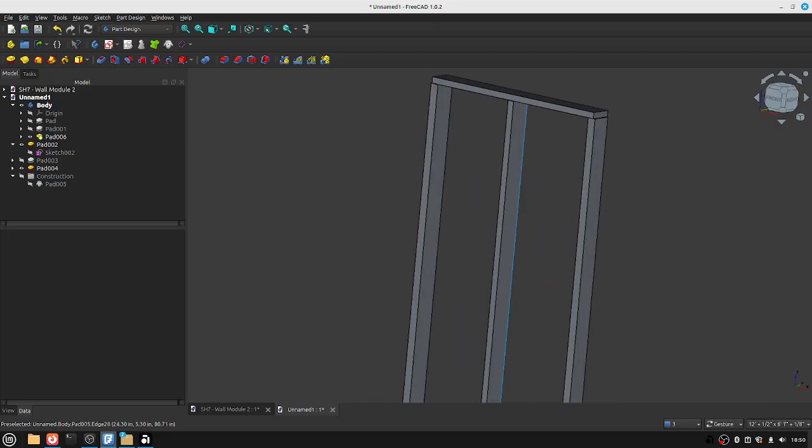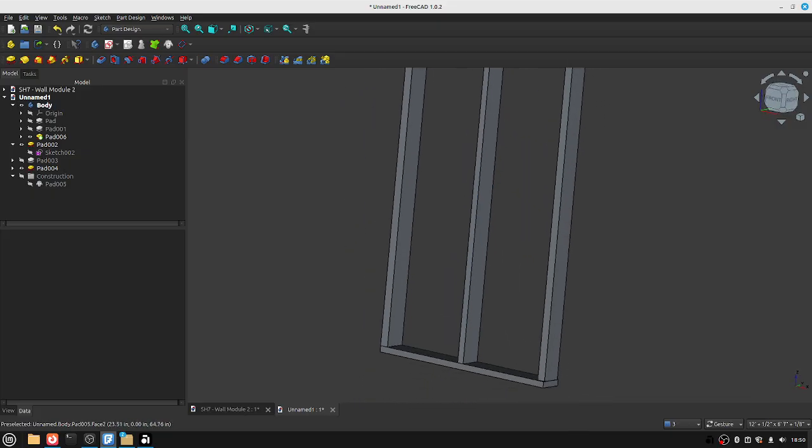So I described here as constructive geometry. You build a sketch, pad it out, and then put pads on. So this is a feature on a feature approach. It does give you the individual parts if you can find them in a part tree. But man, look at all that stuff in that part tree. It's pretty confusing. I don't like it. Hard to navigate. So you can do this, or you can just start individual sketches for each of the parts and do it that way.